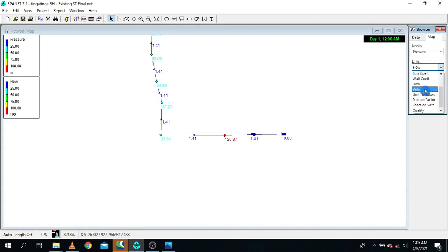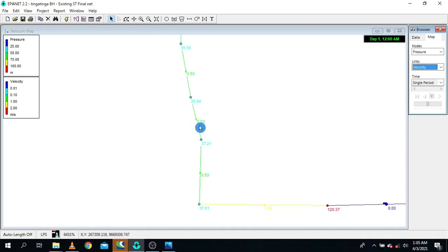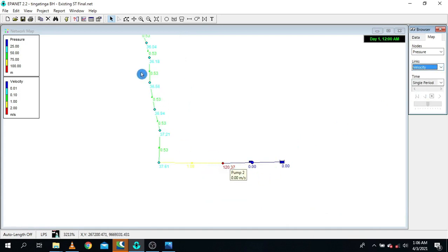Again, if you go here and look at the velocity for case number 2, you have 0.52, while for the first case we had 0.38. That's very important. So for me, I'll just take this one. Even though if you look at the unit head losses, we have 6, of course it's again not that bad. So I'll take this one as my design. I'll use this pump and raiser main pipes, I'll use 2 inches.